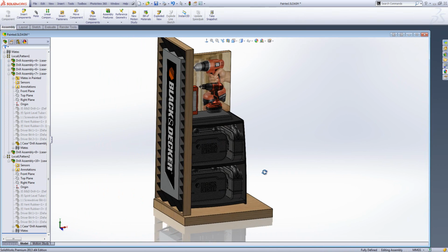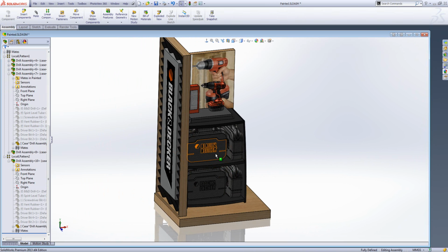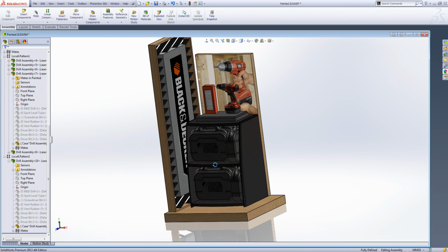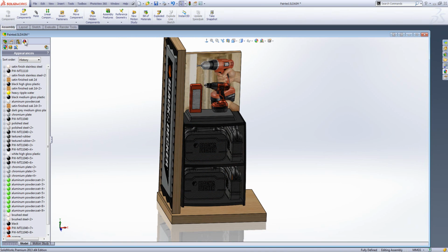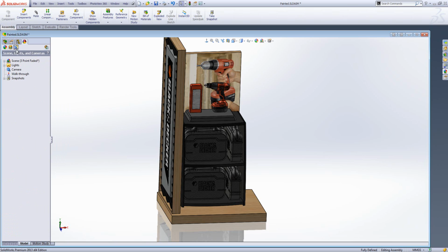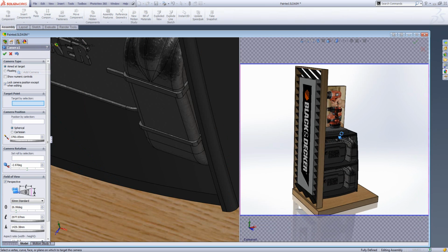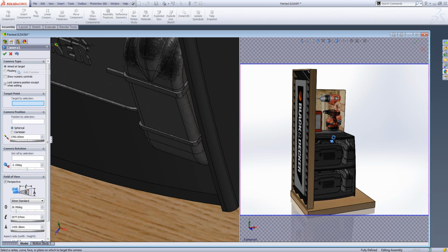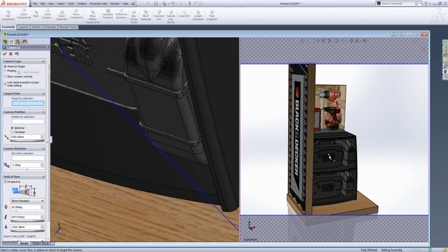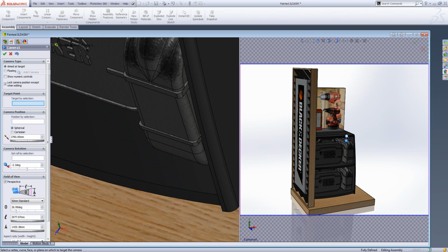Okay, so with it all built up like that, I can go ahead and actually produce some kind of photorealistic render from this design now. If I'm looking to produce some kind of photorealistic output, one of the first things to do is create a camera view, and I'll do that from this display button on the left hand side. I'll just switch through to the camera and right click to add a camera, and that will give me a view of the model, which I can then just rotate manually to pull it into position. You'll notice there's a bit of perspective on the design now, and we can just manually zoom in with the shift key or control to pan just to get it nicely positioned inside that area we're looking to render it.